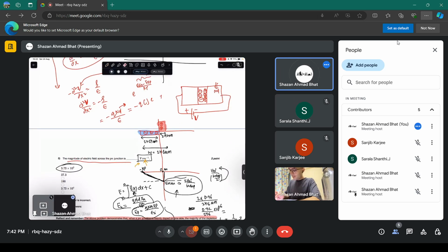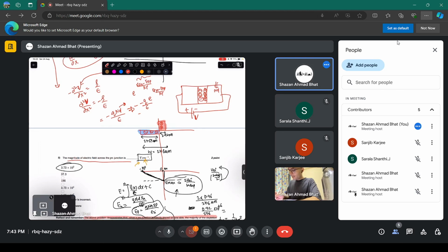So you can write this thing as minus Q times e to the power EFN minus EFP divided by kT, divided by epsilon. And you can convert energy into voltage as Q times V applied divided by kT. Now you get this equation: minus d square V by dx square equals minus Q by epsilon e to the power QV by kT.